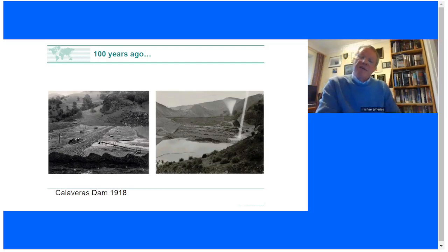And if you consult the transactions of the American Society of Civil Engineers from this era, you'll find these sorts of slides were commonplace. People kept using this method of construction because it was a lot cheaper, but they also accepted a chunk of these dams were going to fall down. Ralph Peck is famously quoted as saying hydraulic fill dams are reliable if they survive construction.